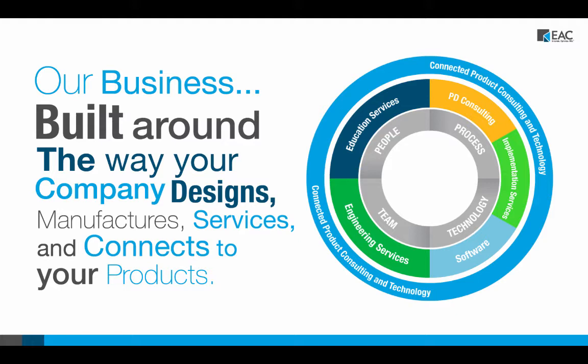Speaking of reaching, there's also a capability of displaying reach envelopes and vision cones. So you can see what the mannequin sees and how far he can reach in doing a particular task. And then under the analysis portion, we can take a look at pushing and pulling, lifting and carrying, and it validates your designs against different types of guidelines.